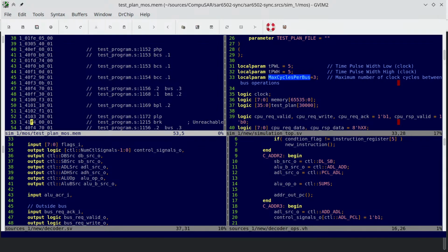So what happens is, if we need to jump over a page boundary, the addresses that have a shared high byte are called a page. So every 256 addresses are a single page. If we need to jump over a page boundary, we need to update the PC program counter high value. And that actually requires another cycle because it needs another ALU operation. So let's do that.